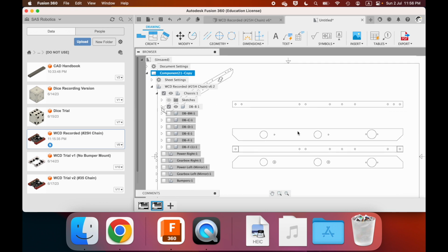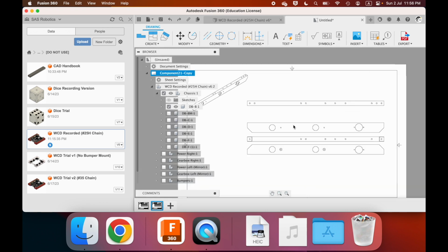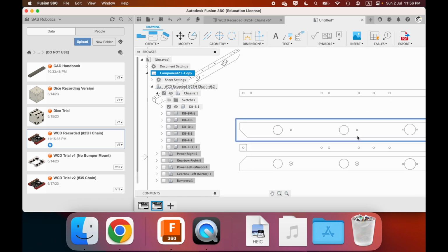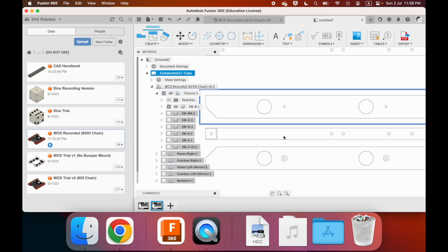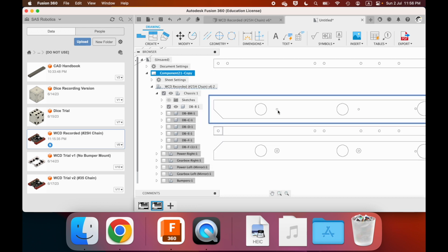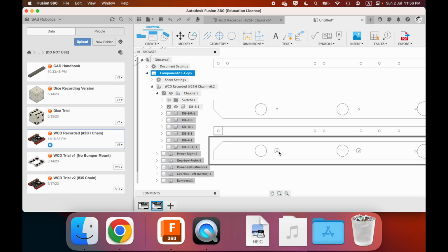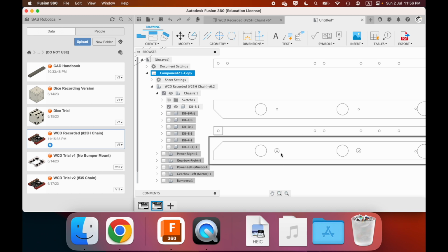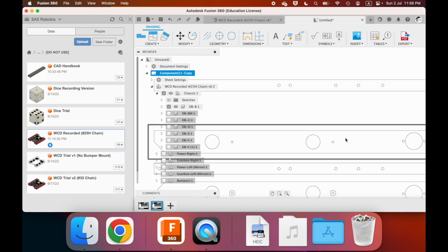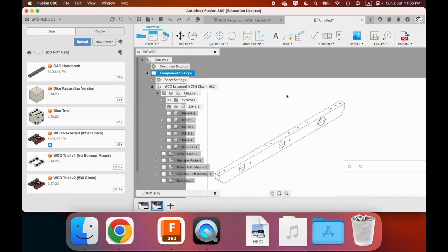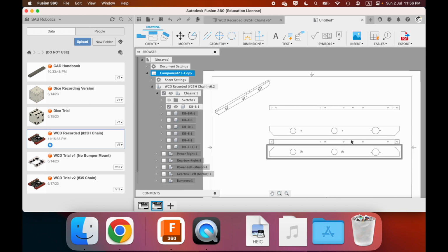Again, the only difference between this and that one is that this fab sheet is a bit more complicated because you have things like different diameters on the same hole. So what you would do is label the position on only one of these faces, but you would also label the diameters on both sides. So you label the diameter here on this side for the smaller hole, on this side label for the larger diameter. Mechanical understands that if they see this, that means drill the bigger hole on this specific side. They can also figure that out by looking at the isometric view.